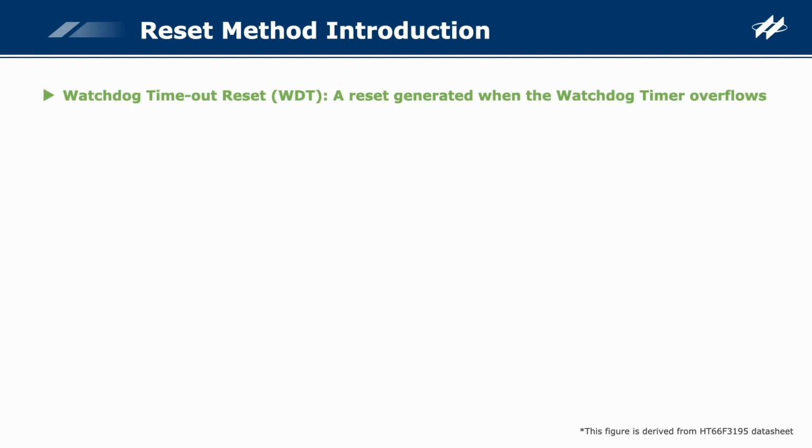Finally, the watchdog timer overflows, causing the system to reset. This reset prevents a crash or external interference from causing the MCU to function improperly. In different operating modes, the initialization status of the watchdog timeout reset is different.